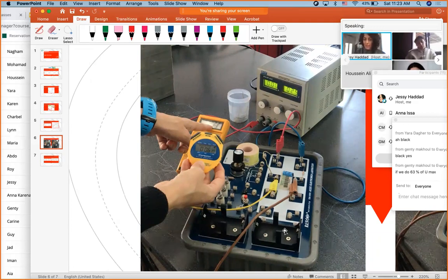I don't like them. As you notice that I'm not using the battery neither for lab 4, neither for lab 5. Why? Because I don't trust their behavior. They don't show any constant behavior. And whenever you're doing a charge and discharge, suddenly at the end of the charge, they stop pushing constantly. All right, which gives you a tail of the chart that is too long, and which means it's going to be very confusing for you if you're going to wait for 5 tau.